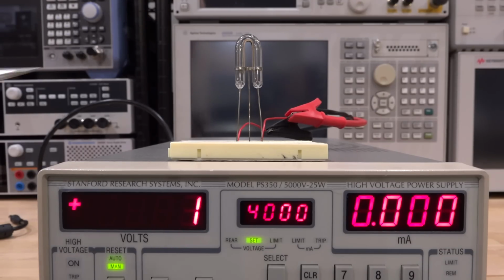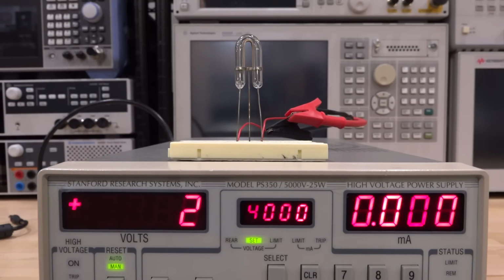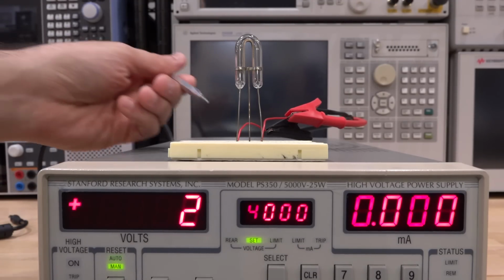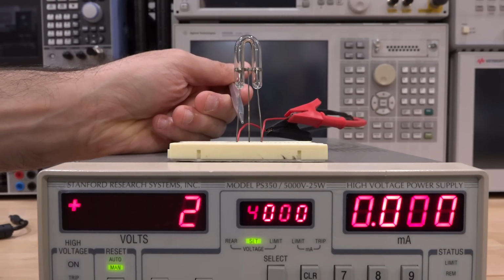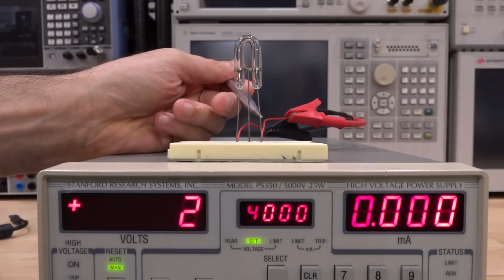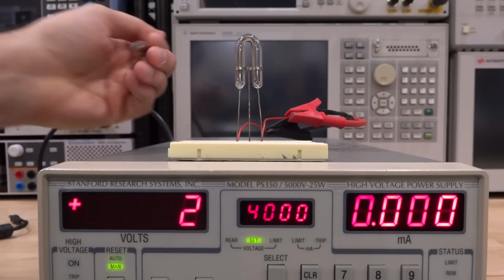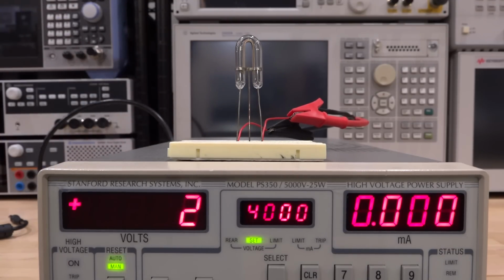So in those situations, they basically put a couple of 100 volts across the 2 main terminals, perhaps by charging a capacitor, and then they briefly apply thousands of volts to the middle port, and that strikes the tube, begins the current flow, and then the resistance of the tube drops drastically, and that's how the capacitor discharges through the tube. If you put thousands of volts across it, and there's a lot of power behind it, you would blow up the tube as soon as you strike it because the resistance will drop, as we saw in the previous one where we had a self-regulating system.